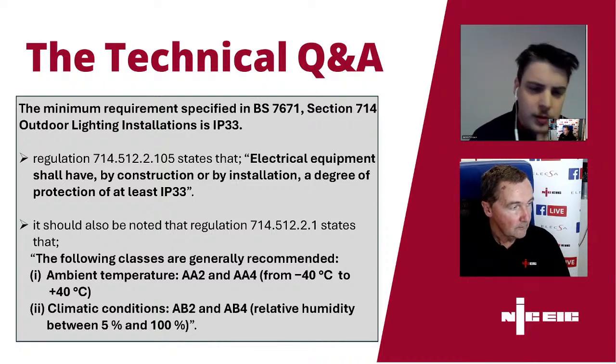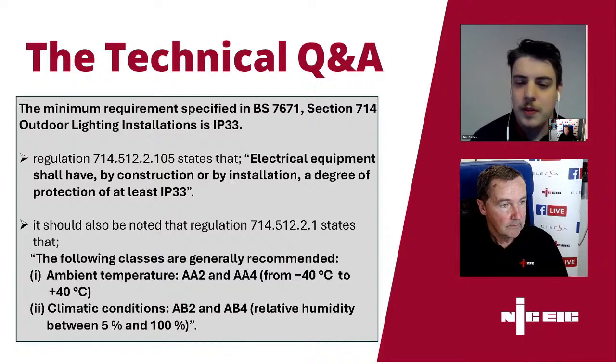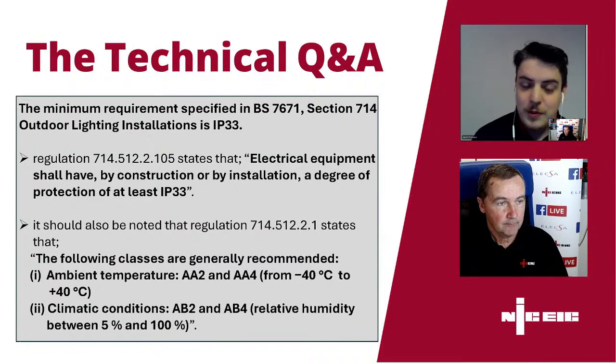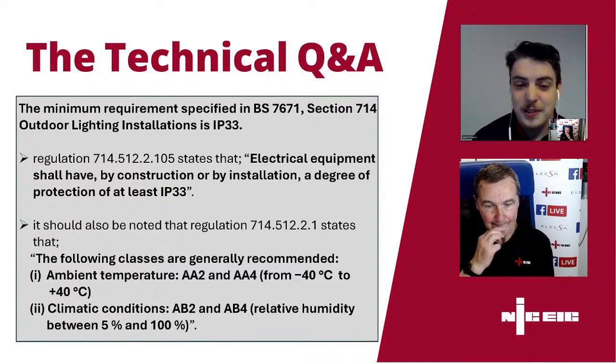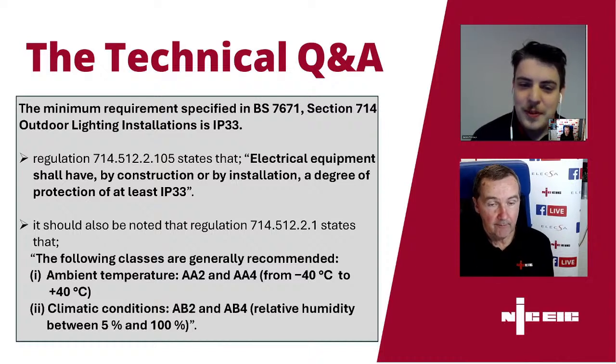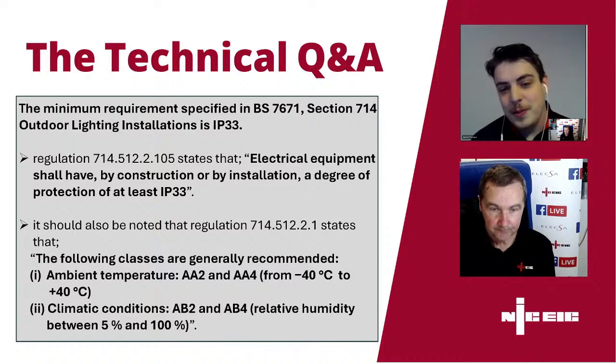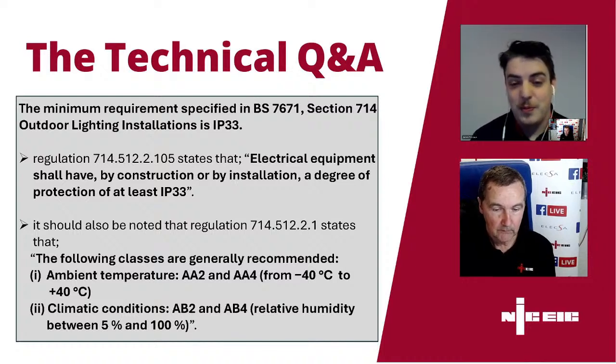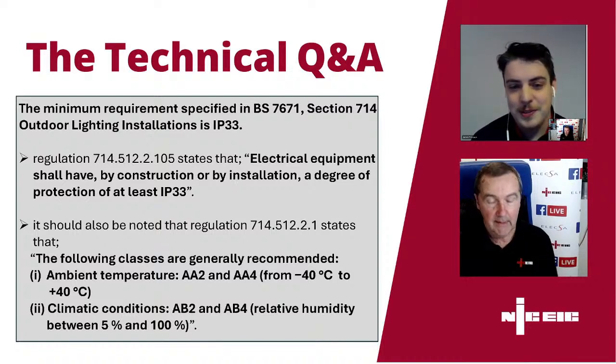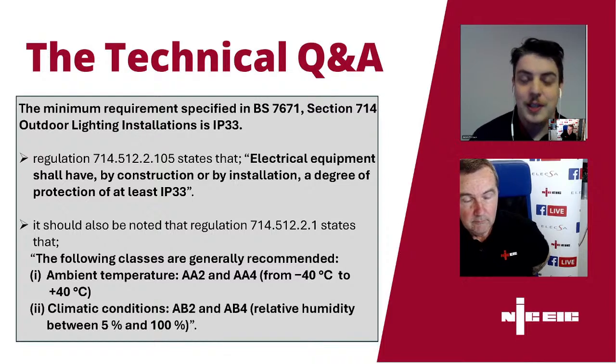Typically how you'd look at that formula, you'd take 50 volts divided by the instantaneous operation of the device, and whatever resistance that is, as long as you're within that, your touch voltage should not exceed 50 volts until it ultimately disconnects. That's the theory behind it. Yeah, so it's the same as supplementary bonding in a bathroom, isn't it? Yeah, 50 volts divided by 5 times 30 on the 6 amp breaker, for instance. And keep your Zs within that.